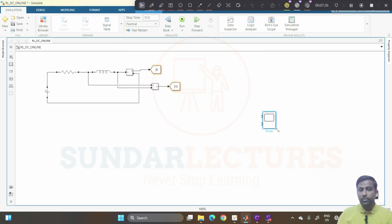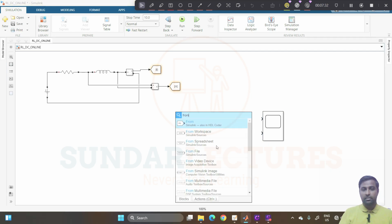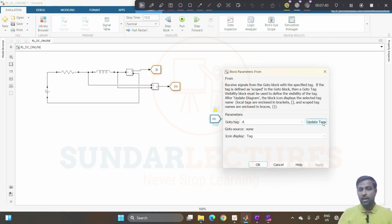Then double click here and get a From block. That will be very easy. Connect this one to this point, go inside this, click update tags. Tags will be updated, and you can see I and V, which is what we have given here.